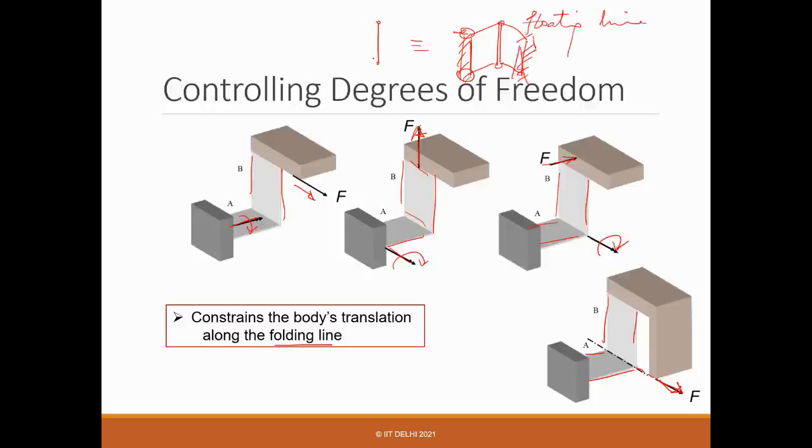So as it deforms, suppose if it's like this and you apply this force, it deforms, right? But then you also get a little shortening, a parasitic motion in the actual direction. But in this case, you don't get that. So it's free of the shortening effect. We call it the shortening effect. And it's mainly because of this floating line constraint.